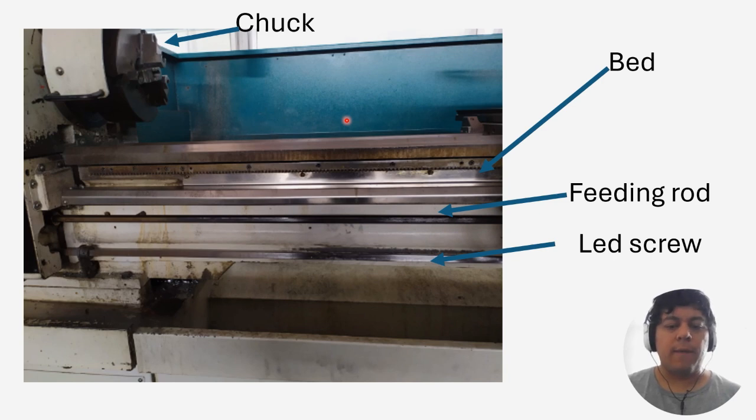After that, we come to the bed. The bed is not the part that's going to hold the material, right? Like I said before, that's the job of the chuck. The bed is only used for us to move the carriage, the saddle as well, which carries the cutting material. So, like I said, let's suppose I'm holding here my piece. I already have the chuck holding the ending part of my material, and let's suppose I don't want to start manufacturing from here, but I would like to start manufacturing from this point. So that's the bed, all right. That's going to allow me to move the carriage.